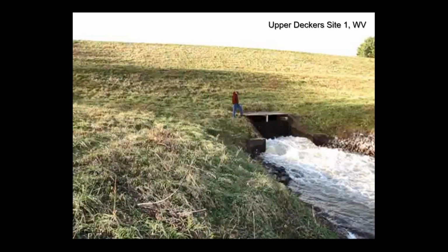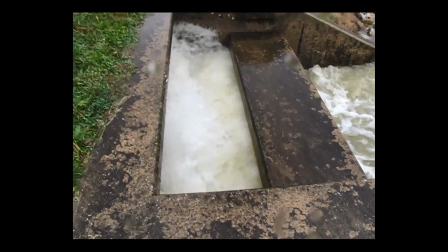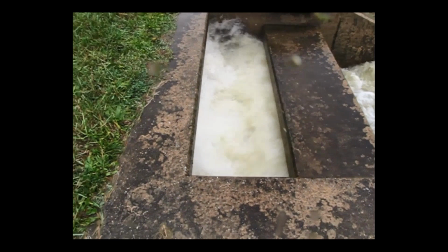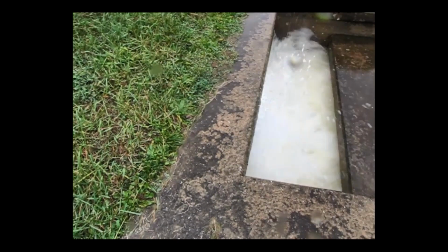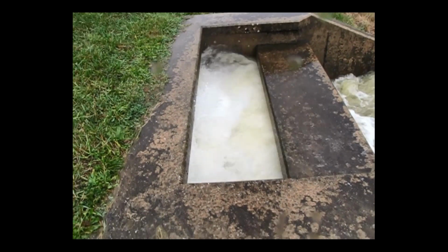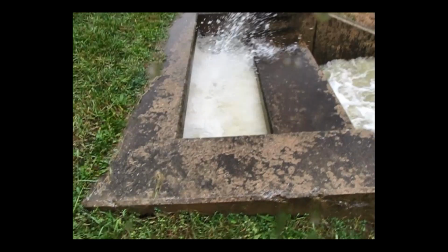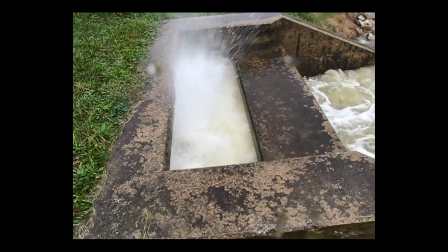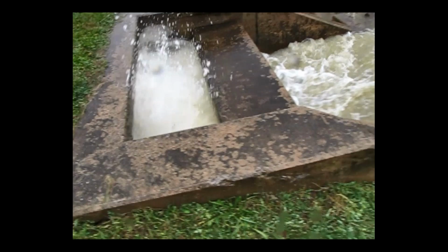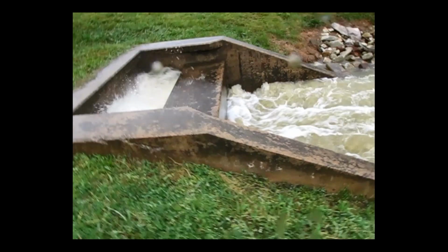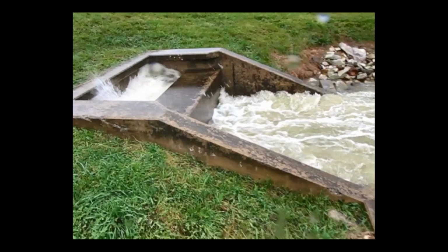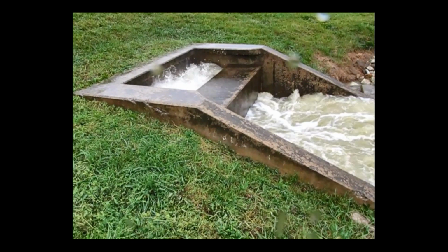Now, here we're just looking at the outlet, but here's a video that shows really what's going on. So this one doesn't have a covering on it, but you can see that high velocity flow impacting the wall in the impact basin, and highly turbulent, and dissipating the energy so that the flow that's leaving is a lower velocity and doesn't cause erosion of the outlet.